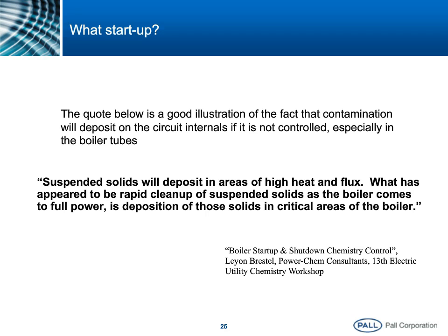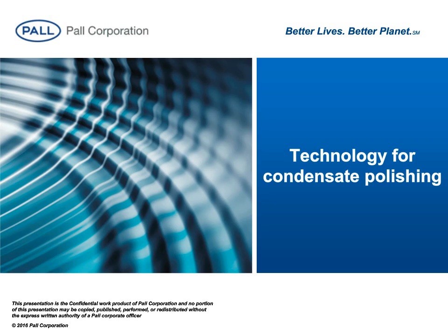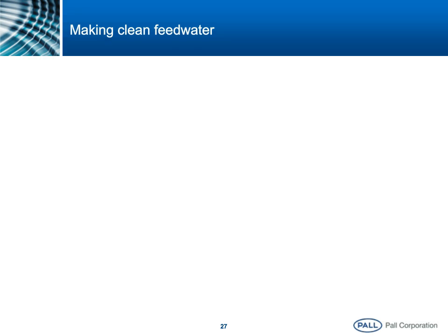Okay, so now I want to move on to potential solutions. Let's spend a little time talking about technology for condensate polishing. In general, making clean feed water is really about using a combination of demineralizers and filters.